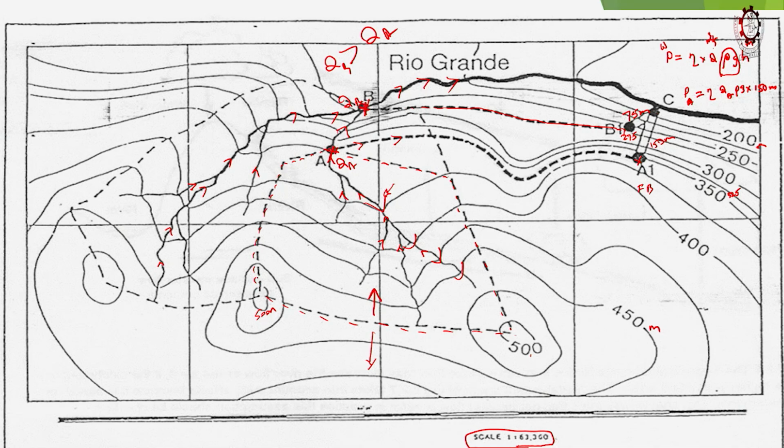And here also you can see there are hilltops, and water into this river system goes from here to there. If the rain falls here, that water goes into this river system. If the water falls here, water goes into this river system. And also incidentally we note that at the catchment boundaries, contours are in the other direction compared to the contour shape in the river, right. Here also you can see. So, you can use all this knowledge in marking the catchment area boundaries: rivers this way, contours this way.